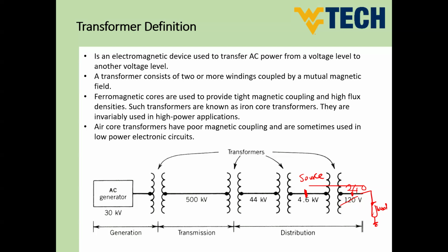So all of these types, guys, are three-phase transformers. These are not single-phase transformers, because we generate the power in three-phase form, not single-phase form. However, for light loads, we use single-phase circuits. But if the load is heavy, we have to transfer to three-phase. By experience, you can say, if the load is more than 6 kilowatt, for instance, we can transfer from single phase to three phase. For that, most high power devices are three-phase devices.